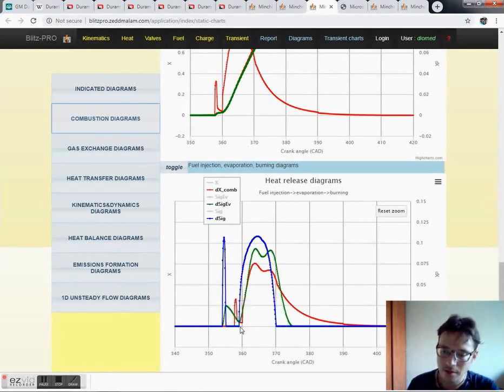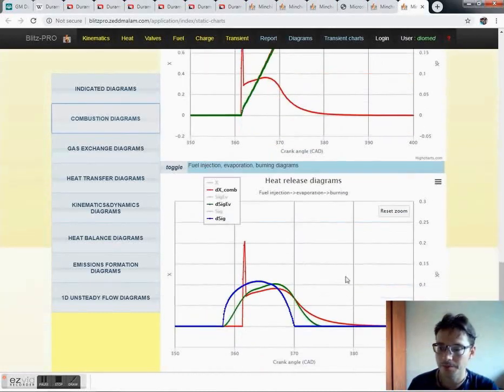So the ignition delay for this second injection, as you can see, is very small. So there is not so much fuel vapor which occurs during this ignition delay, and combustion is very smooth and fast together. So we can compare it with this combustion diagram, for single injection, when we had so long an ignition delay and so rapid combustion at the first stage.